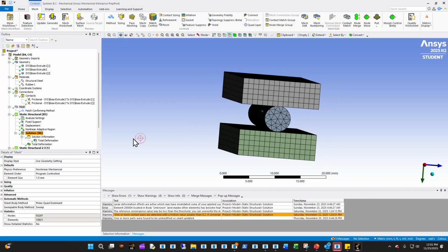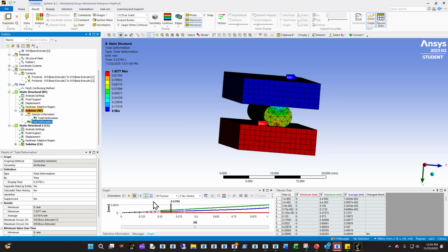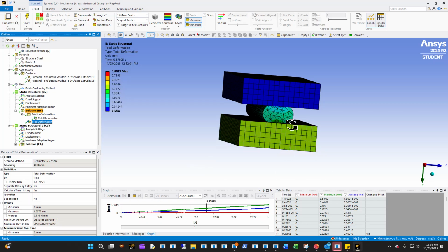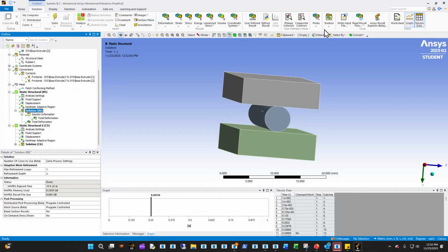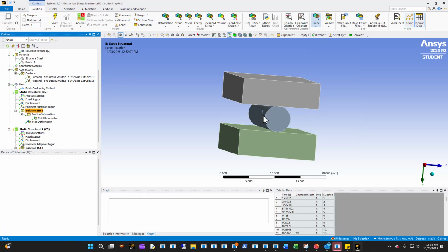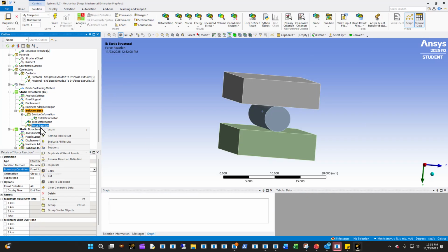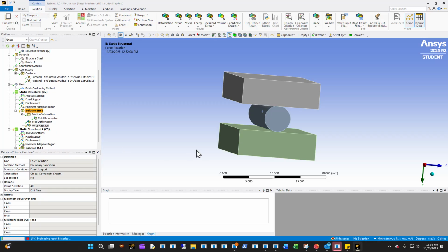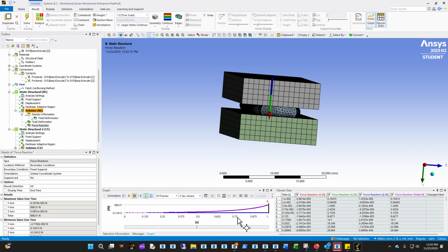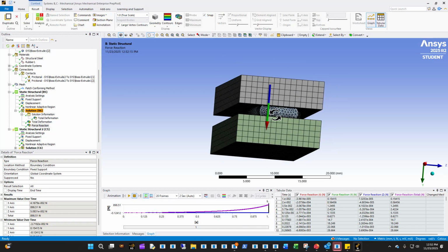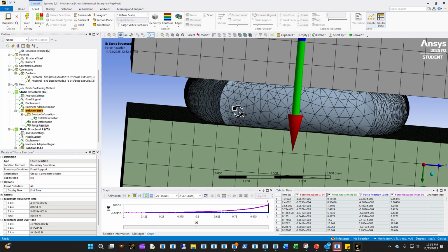Otherwise, it's pretty basic. As you can see, once it's set up, I have this type of response, which basically remeshes as it deforms to maintain element quality, right? So you get a pretty decent element quality. I can also check reaction forces on my fixed support. I haven't checked this, but you can check it. It should give you a hyperelastic compression curve, which is like exponential growth, right? Looks like that.